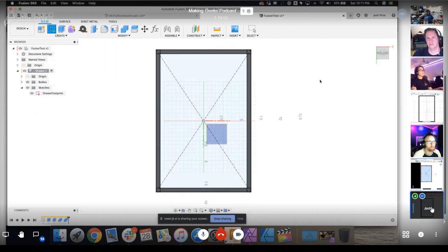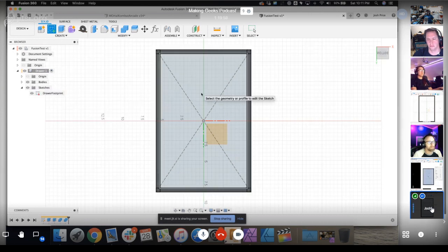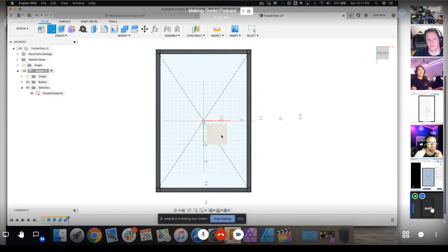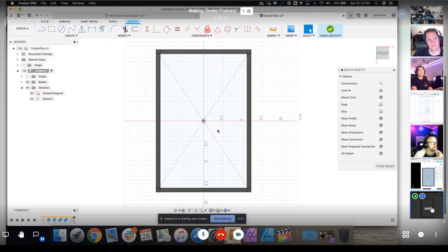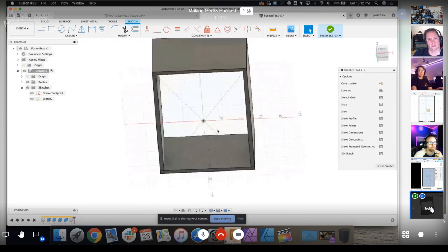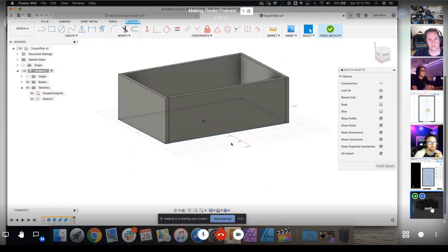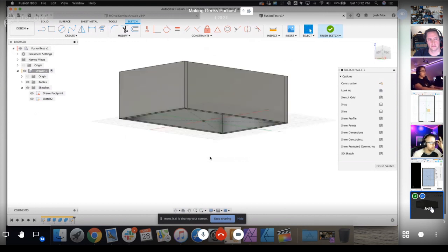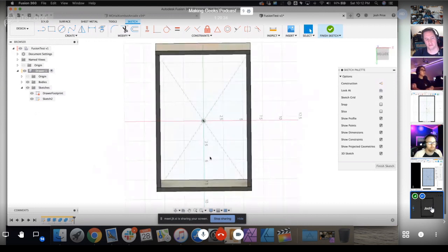And now our origin plane, we can create a sketch back on the floor because we're looking on the bottom. So these are the bottom edges. You can create a sketch just on this one little wall or just on this little corner of a wall. On any face, any planar face, you can create a sketch. Because I know that all these were actually done on the floor, I'm just going to put the floor. There you go. So it shows that the sketch is now on the bottom of my box because this is actually the same plane and we went up. So now we're just going to go on the underside of that plane, if that makes any sense.